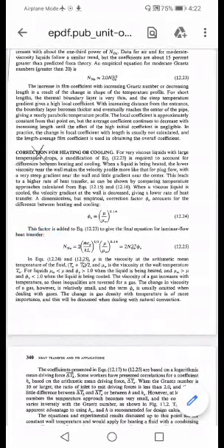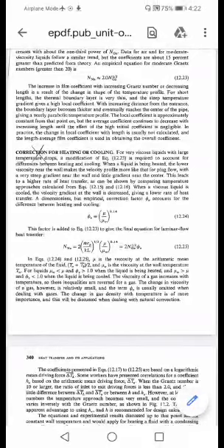So this is the correction factor phi e equal to mu upon mu w raised to 0.14, where mu is the bulk viscosity and mu w is the viscosity at the wall. It is very clear that whenever a hot or cold fluid is passing through the tube, due to heating or cooling the viscosity is going to change. As I said earlier, the viscosity is very sensitive to temperature. So as temperature increases, the viscosity decreases, and thus the rate of heat transfer is also going to change.